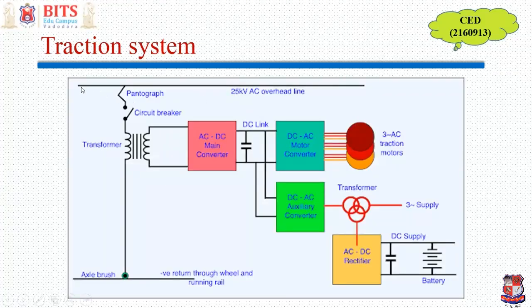I have a top wire, known as the conductor wire, at a voltage of 25,000 volt, 50 hertz single phase, right? We use only single phase supply because it is very costly to run 3 wires for hundreds of kilometers. The circuit is completed, or the return wire is, through the tracks, that is the rails.